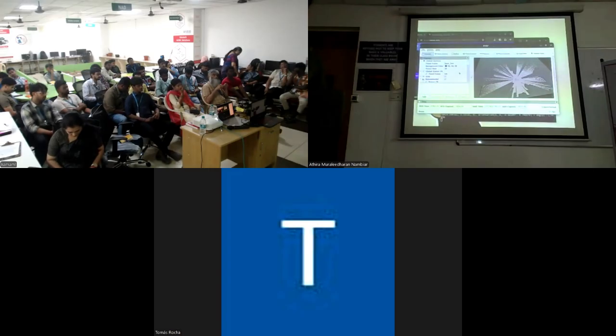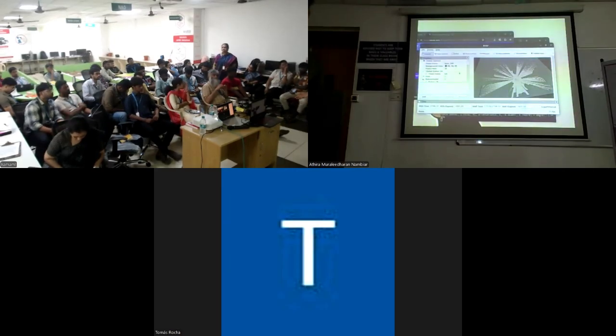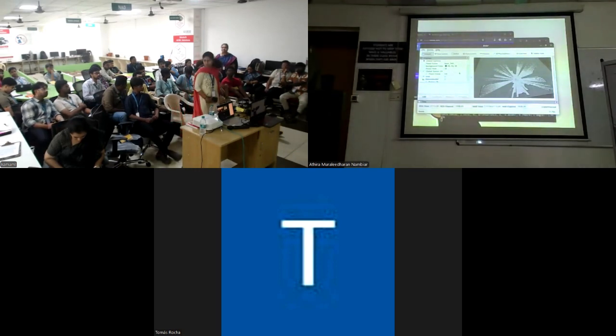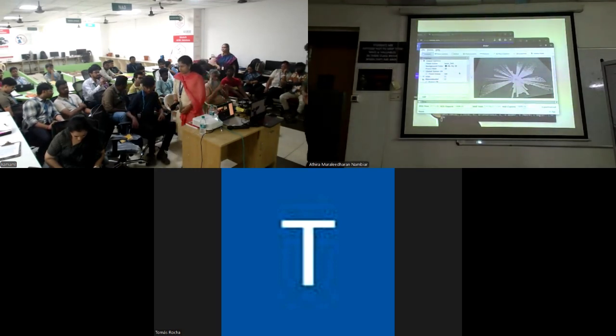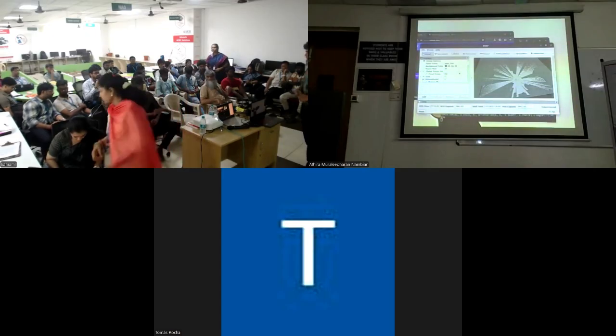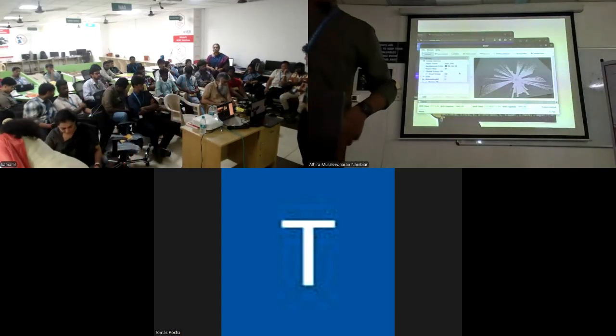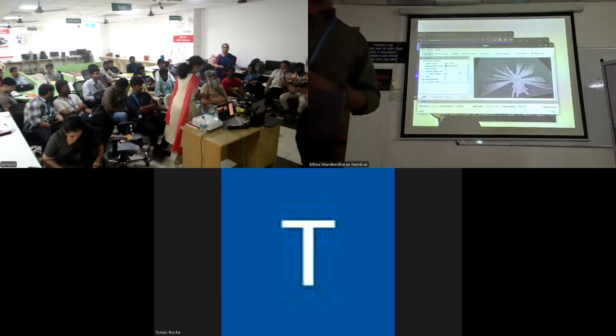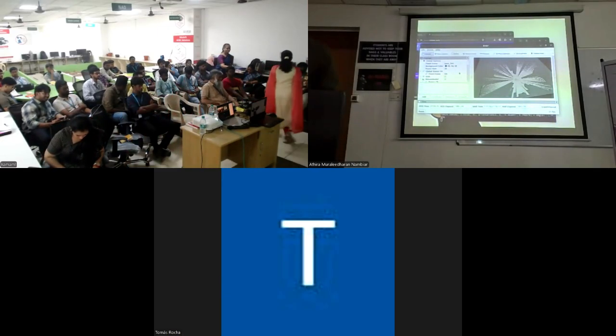A 3D LiDAR can also mimic it, but 3D LiDARs are currently way more costly. So instead of this, if we add a camera, it can mimic what a 3D LiDAR does, and the camera outputs will also be shown in our interface. So you said 3D LiDAR and camera for 3D LiDAR. Somewhat, maybe. A 3D LiDAR can also capture what's behind it, the 3D objects. The camera will have to turn, but it is way more cost effective.